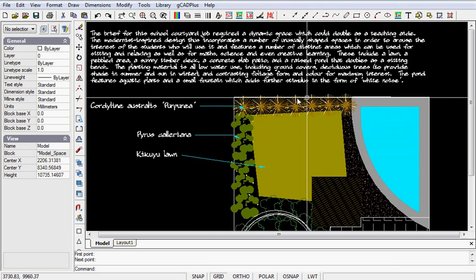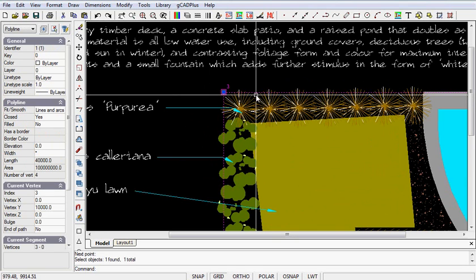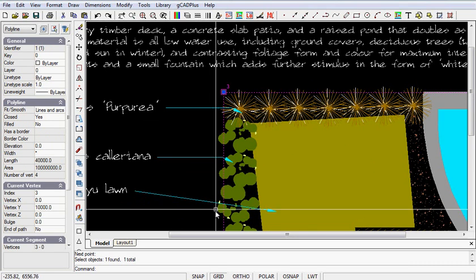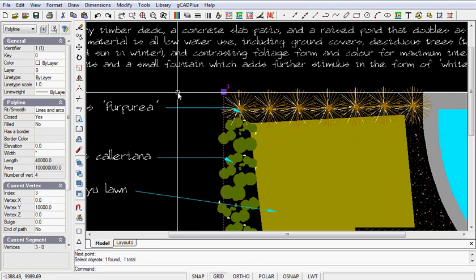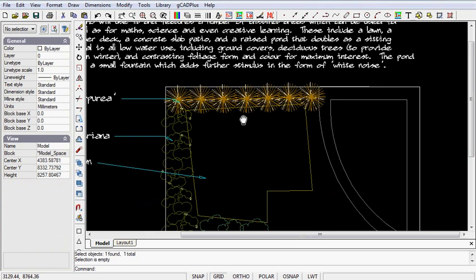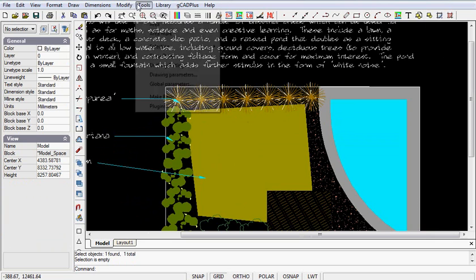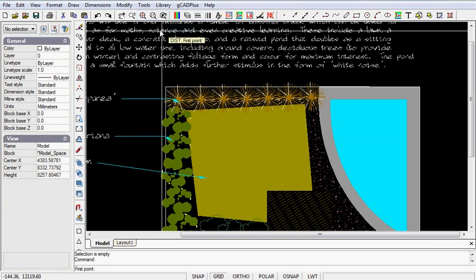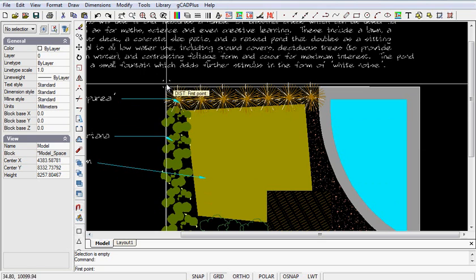If I wanted to measure that distance accurately, there are a number of ways to do it. I could select the line that represents that boundary, but you can see it's a compound line. It moves around the corner, so to speak. Let's unselect it, and just zoom out a little so we can see the entire line. I can say Tools, Distance, I'm going to measure from. So down the bottom here in my computer, I've got a little square box. That's called an object snap. So I can snap to the end point of the line.